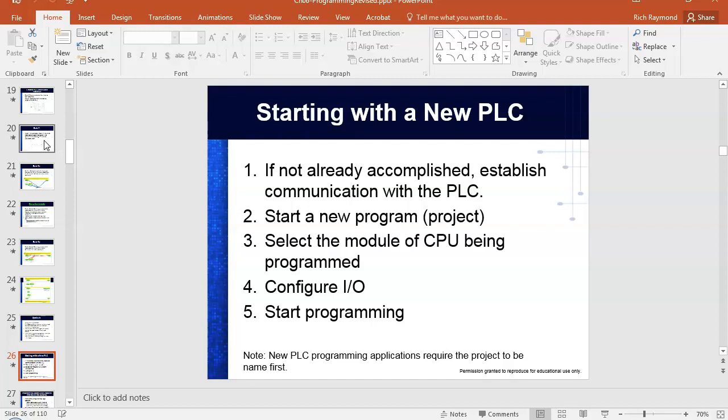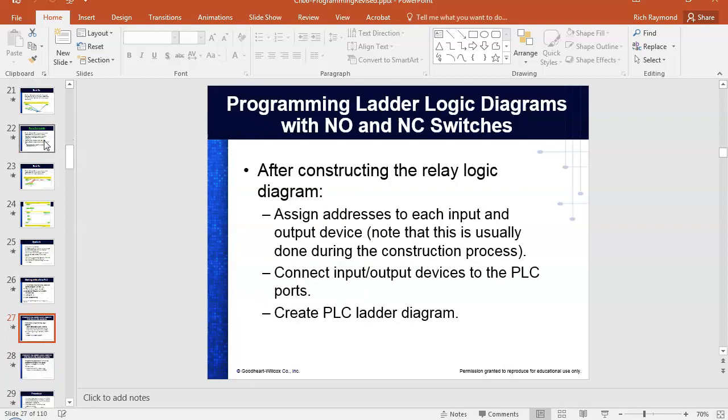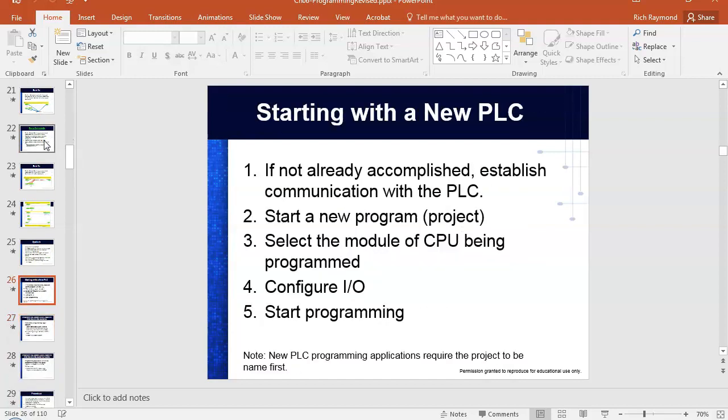the CPU, configure the I/O, which we haven't talked about. I'll show y'all what you do at that. So right now, these are modular PLCs, but they're what I call hybrid, which means they come with a few internal input ports and a few internal output ports. Then on the right hand side, we could add up to 5 modules onto this PLC, which makes it a